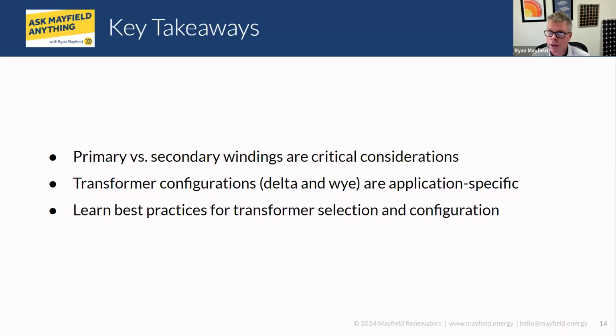One of the things we have to consider is, my answer is going to be no, but I'm going to look to the group to see if there's anything that I'm missing here. One of the big things is the ground fault protection. If we put the delta on the PV side, we're going to have to add a way of doing some ground fault protection, because there's not that neutral reference, there's not that ground reference. So having the Y on the PV side is an absolute requirement because of having that reference and being able to use the ground fault protection schemes in those inverters and making sure that they're working properly.